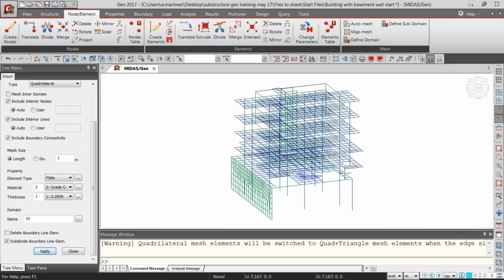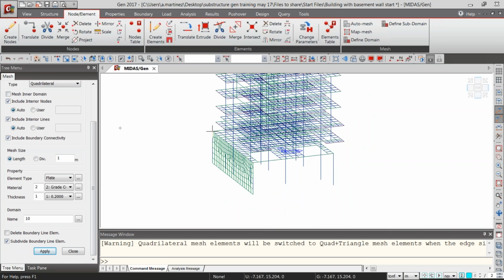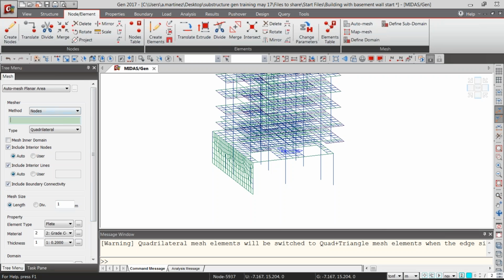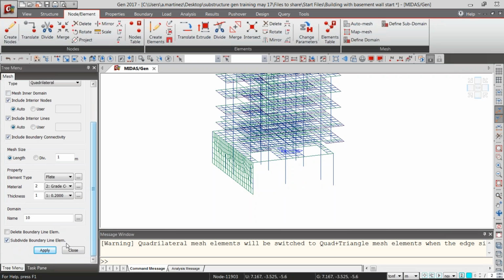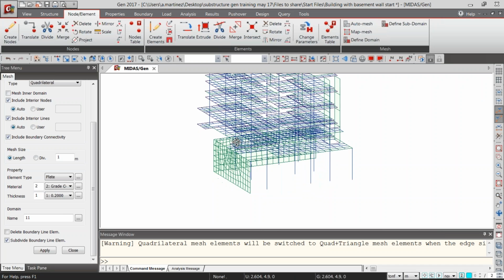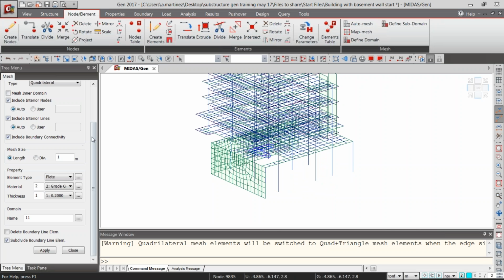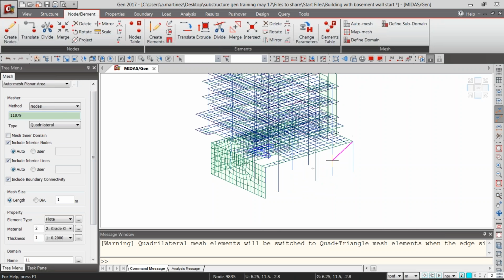In order to keep the local axis directions consistent for the walls, so that when you apply boundary conditions and loads, positive is always an outward or inward normal force or normal direction, you want to keep doing it in the same direction when you're meshing these elements. So I'm consistently going counterclockwise when selecting the four corners.